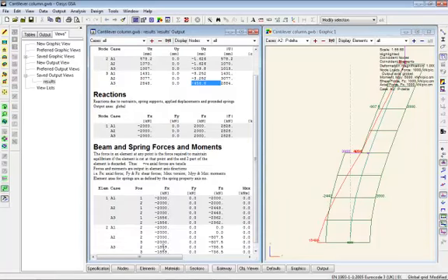Likewise, we are getting interchange between the axial loads and the shear force, which we are not getting on the other load cases. So for a large deflection structure like this, the non-linear is giving us much more sensible looking results.